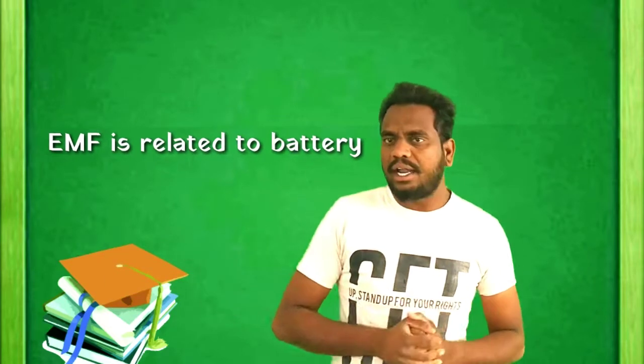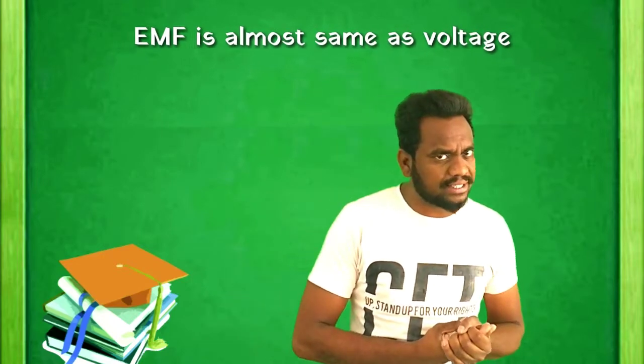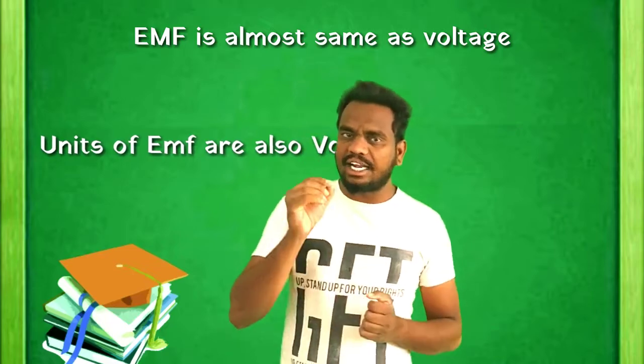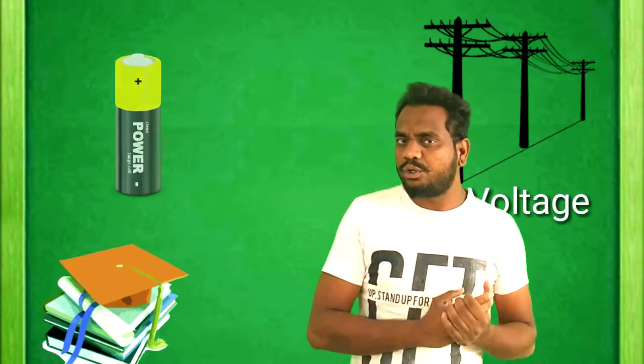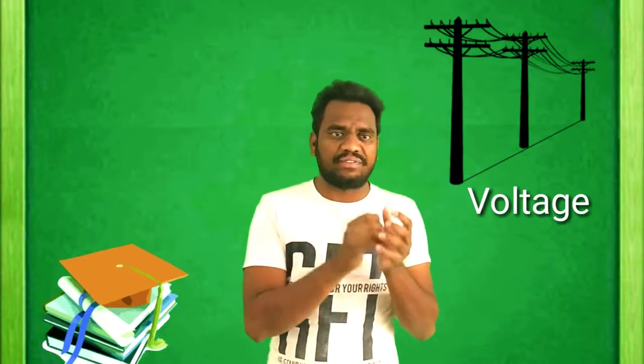So firstly, coming to the EMF. Guys, you know very well EMF is something which is related to a battery. But EMF is quite similar to voltage, that is potential difference. As you know, EMF's unit is also volts. It is also measured with a device called a voltmeter. But the difference is EMF is considered for a battery, whereas voltage is considered for any current carrying conductor. Now today we will discuss the main difference between voltage and EMF.